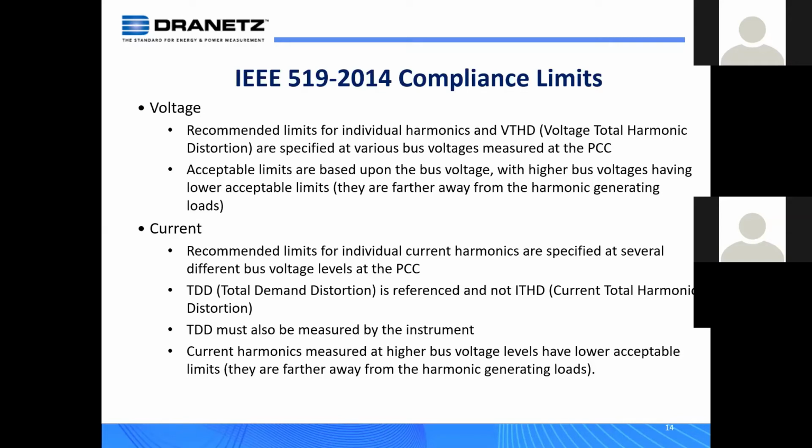And the reason for the various bus voltages, and you'll also see that for current, is really this one theory. And as I said before, the loads that we plug into the power system are the ones that create the harmonic problems. It's the way current is drawn from all the electronic and other loads that we plug in. So harmonics are not generated from the generators of power. They're not created there. It's the consumers of power.